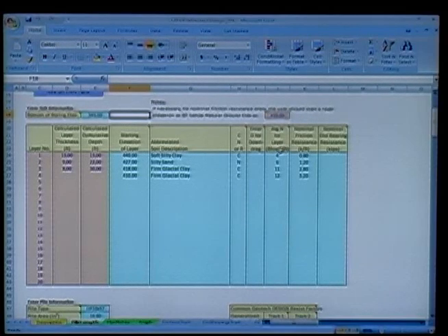You put in your average Ns for however you want to break up the data you get from the geotech guys. If you want to split it up into up to 20 layers, I guess you can do that. My guess is you'll get away with 4 or 5 or 6. Nominal friction resistance, that's where you go to the chart in the blue book, grab those values, plug them in. If you have end bearing, you can put in multiple values of end bearing. The sheet will figure out how far the pile has to go, and if you have end bearing on every layer, wherever it needs to stop, it'll use the end bearing in that layer where it stopped. In this case, we didn't have any end bearing.